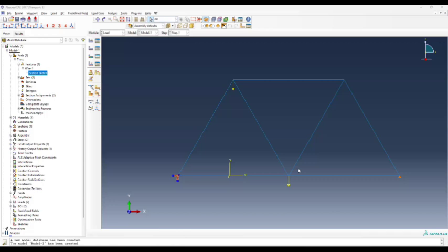So some boundary conditions you have to kind of set up differently depending on the nature of them. So the fixed support, because it's something inherent to the actual setup of the problem, you have to prescribe it in the initialization step. Because it's restricted in all degrees of freedom across. But the other one, in the initialization of the problem, this roller could move. But once the problem starts and we actually start accounting for the loads, the roller can't move. It's just a different kind of nature of the boundary condition. Does that make sense? Yeah, thank you.